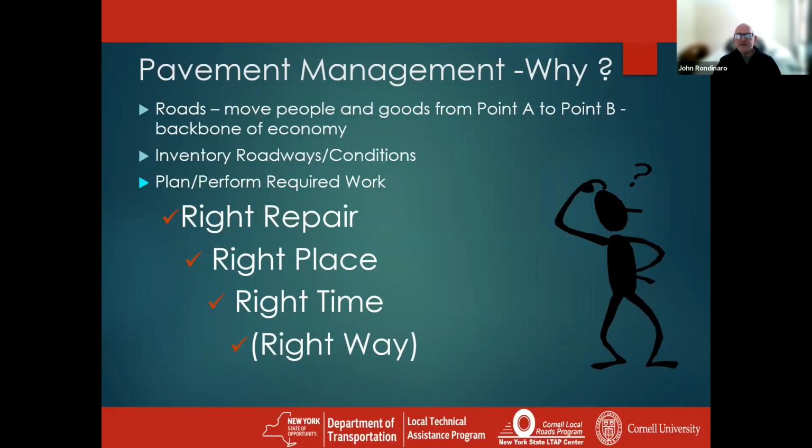And the way we do that is by the use of pavement management. We use any form of a system that inventories your roadways and conditions, and then allows you to plan and perform the required work. And it revolves around the key principles of right repair, right place, right time, and my own favorite add to this, right way.